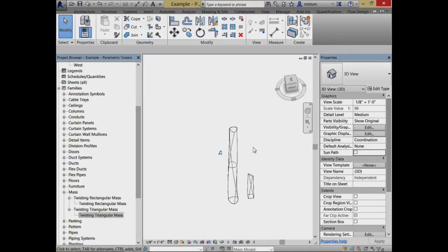I can take that and look at it from a solar radiation standpoint. Given this shape, what's going to happen in terms of the insolation on the glass that we're going to have to ultimately deal with? Or even start to think about, based on how this building is oriented, it's not completely uniform. Maybe I need to add shades to one side of the building based on the solar radiation, but not on the other side. As we move up the tower, maybe it becomes a very custom thing where different panels on different parts of the building have different sizes or different shading distances to accommodate that. And that's the kind of stuff we can get to by doing a little bit of programming.